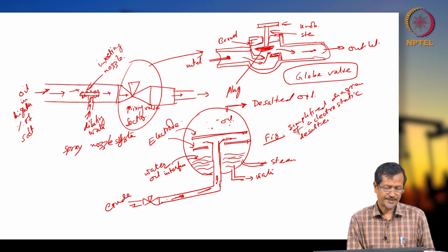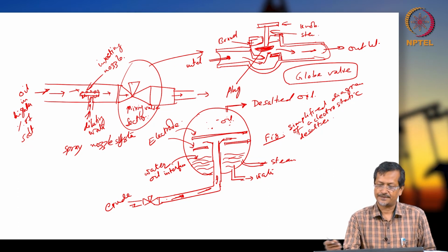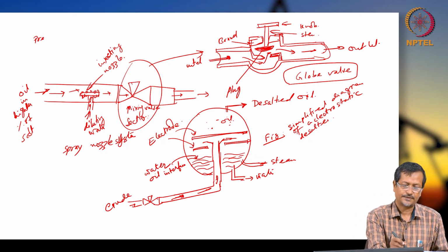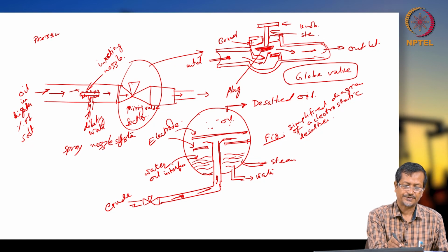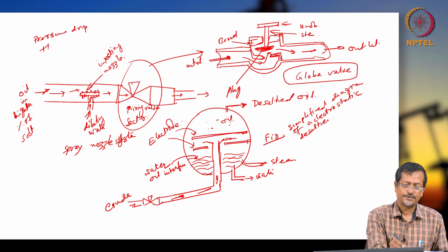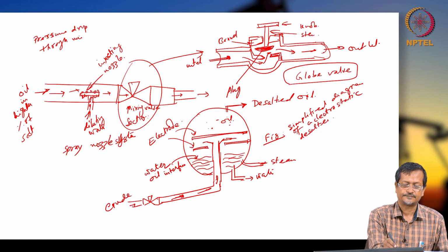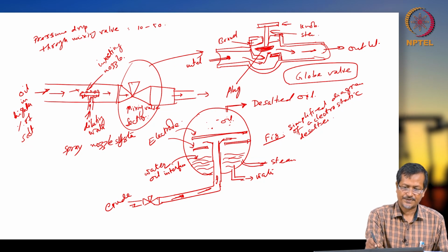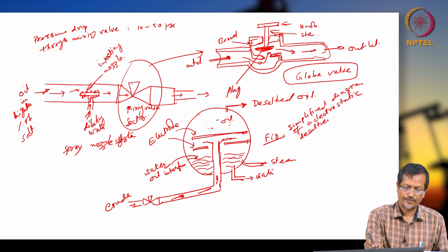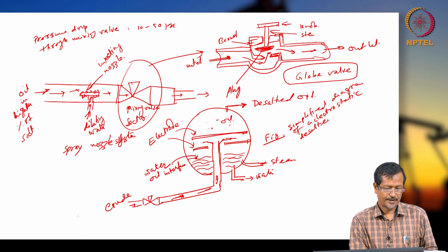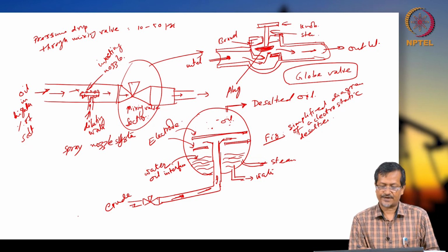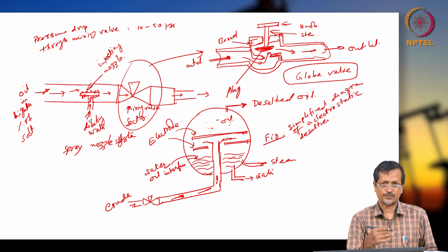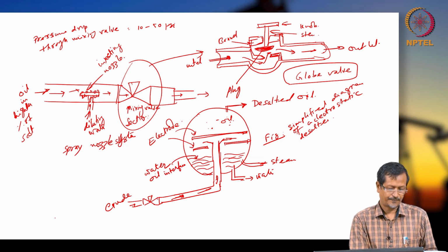Pressure drop through the mixing valve varies from 10 to 50 psi, okay. The required pressure drop can decrease by installing a pre-mixing device. In that case we have a pre-mixing device, like a nozzle we have put, so this is reducing your pressure drop.